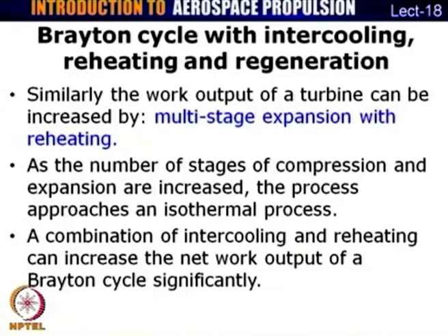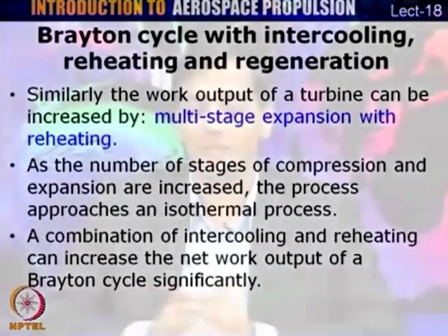But what we shall see a little later on is that using either intercooling alone or reheating alone is not sufficient. It is also necessary that we use some amount of regeneration as well, so that the overall cycle efficiency can be improved. So, intercooling plus reheating with regeneration is one of the mechanisms by which one can increase the efficiency of a Brayton cycle significantly.